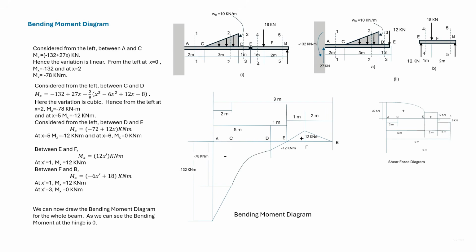Here we notice a few things looking at the shear force and the bending moment diagram for this problem. Earlier we dealt with uniformly distributed load, and we found that the shear force corresponding to the uniformly distributed load was linear and the bending moment was quadratic.